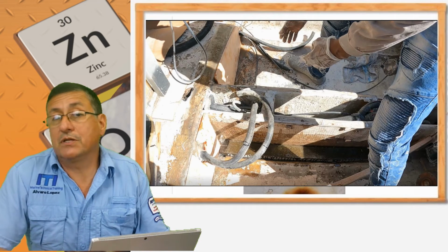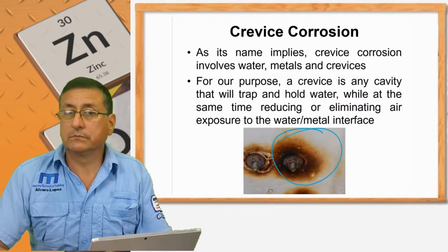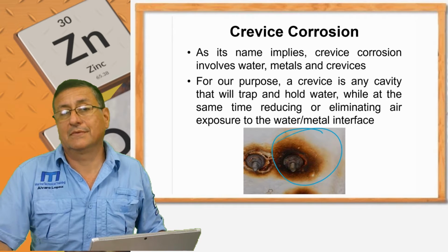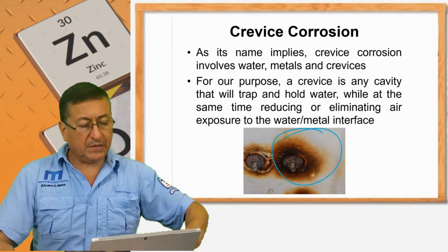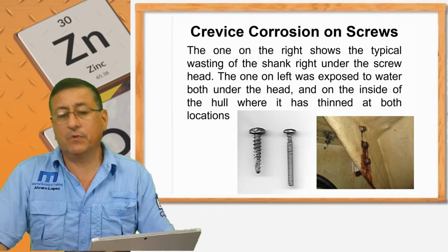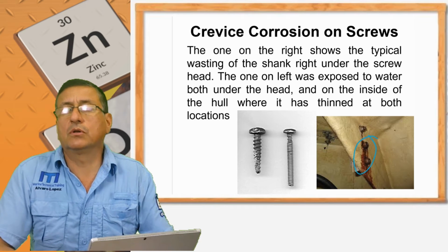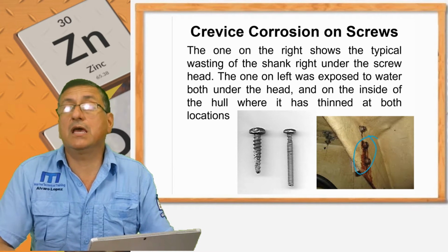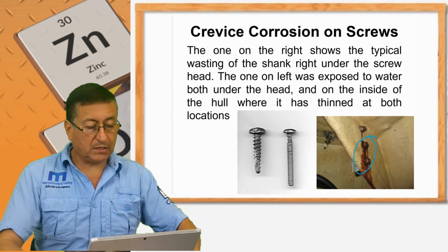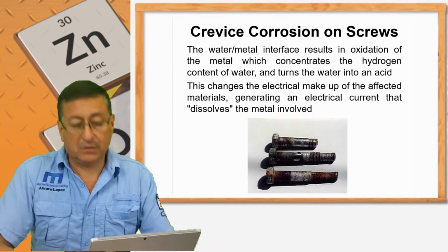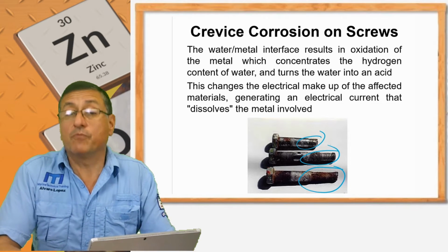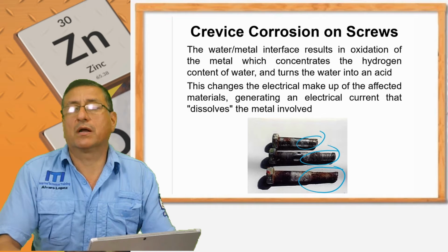Heavy job. Yes, because people use improper hardware. Be careful with that. This is the most common problem: the selection of the hardware. Basically, the problem starts because people use regular screws, regular bolts, and regular washers, and not marine grade. Remember, marine grade should be 302, 304 stainless steel, series 18-8, 18-10, marine grade. Otherwise, at the end, all of the bolts will be destroyed by crevice corrosion, and the threads, and you have a lot of problems when you select improper hardware, improper material.